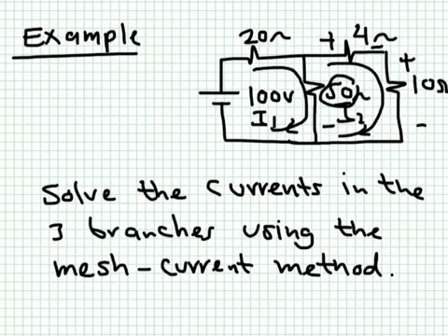It's going to be plus and minus. Okay, so we can write the same equation here. We can simply say that 10I2 coming from this one plus 4I2 coming from this one plus 5I2 coming from this one minus 5I1 coming from I1 flowing through the 5 ohm is equal to 0.